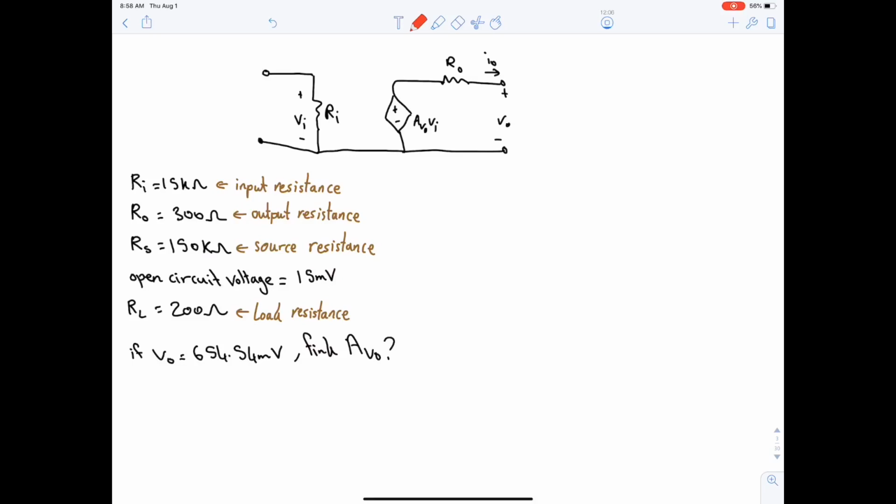Next question. Okay, that's an amplifier. Whenever you have such a question, you always have to do two things: connect the input and connect the output. Output is simple, it's always a load resistance, and on the input you either have to put a voltage source and a resistance or a current source and a resistance. Here you have voltage, hence it should be a voltage source and a resistance in series. RS source resistance and VS voltage source.